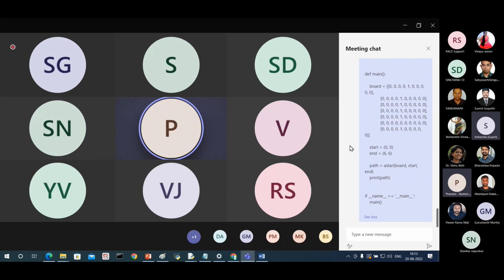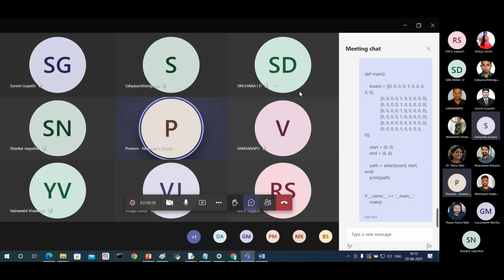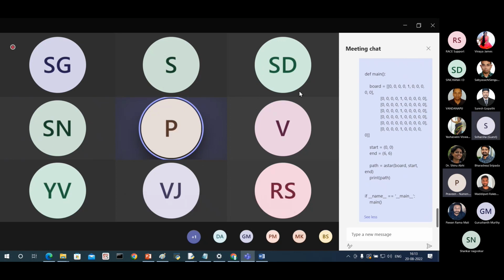Now let us see the rapidly-exploring random trees algorithm, which is also used. See, in the A-star algorithm, the number of blocks are known in the given configuration space. For a given configuration space, as the granularity is also known, the number of blocks to cover the path also will be known, and the open set is very definite here. The open set is definite.